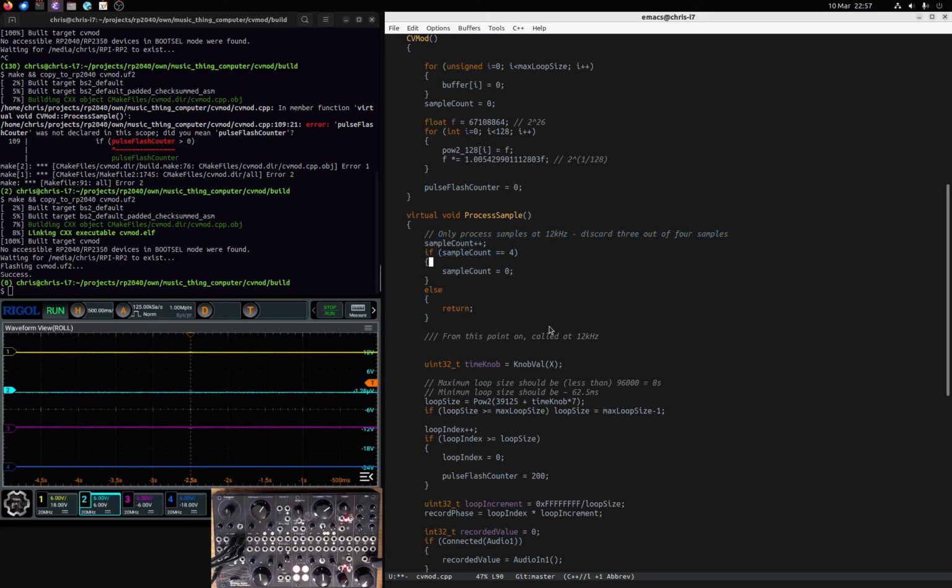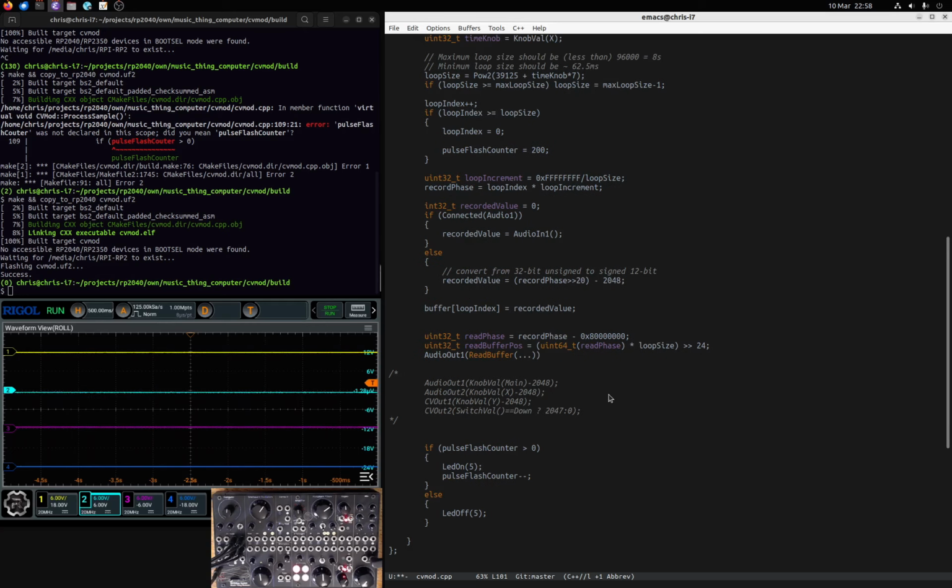So really, we're trying to do all of this in one 48 kilohertz sample, but we're really only processing the samples in a meaningful way at 12 kilohertz. So if we do end up with performance problems, we can, by utilizing the second core, get around this and have the full 12 kilohertz to do this work. But we'll see if there are problems before we go there.